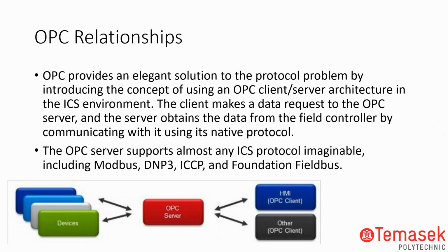So it's possible to have this OPC server that allows you to communicate with all kinds of OPC clients and devices. The rest of the other protocols can sit over OPC and be carried over it; you just translate into OPC and carry all the transmission data over it.